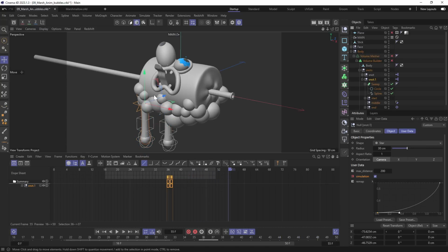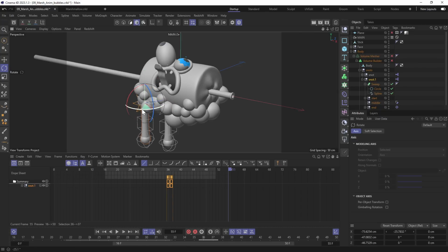And then I'll add some uniqueness, maybe rotate it a little. You can shift frames in time and also scale it a bit. If you're gonna scale it, make sure you use object mode. This way you will change the local coordinates of the object.